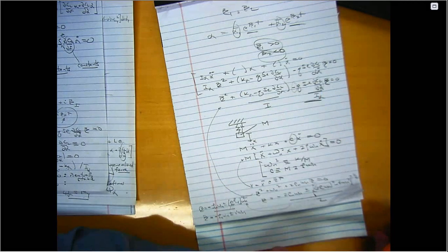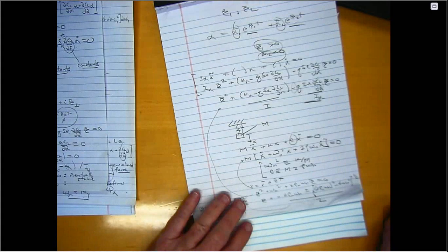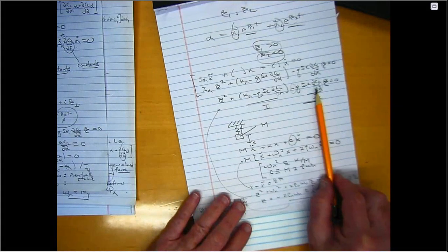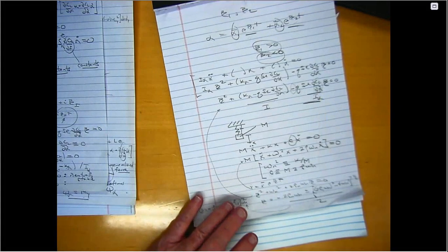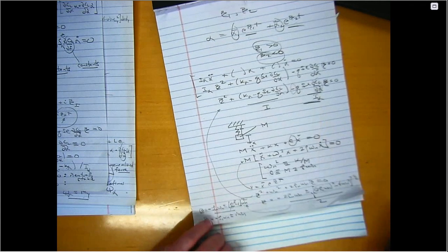So if I had some structural damping, and it was positive, then it might offset the negative aerodynamic damping. And people, when they design turbo blades, put in structural dampers and use the structural damping. One reason they do that is to offset the possible negative effects of negative aerodynamic damping. Absolutely.